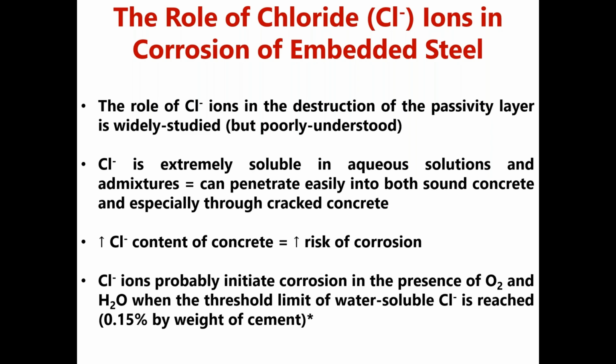So a lot of this is kind of theoretical discussion, but we're pretty certain of these relationships we're discussing. Also note that the presence of oxygen and water have a lot to do with how much chloride you can have in the concrete or in the cement before it starts being a problem.